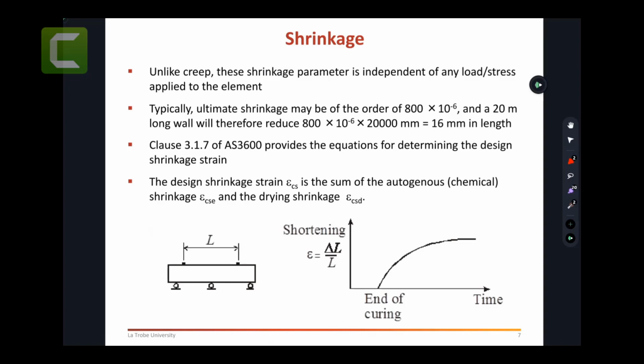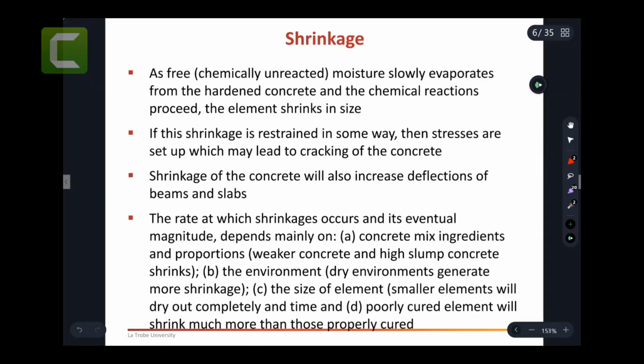It's just a strain value, which is well defined in the standards. And if you're going to use this, the people who are going to supply the concrete will make sure that their material follows such a parameter. That's what you need to adopt as a designer, and consider when you do the calculations or when you pick numbers from the standard.